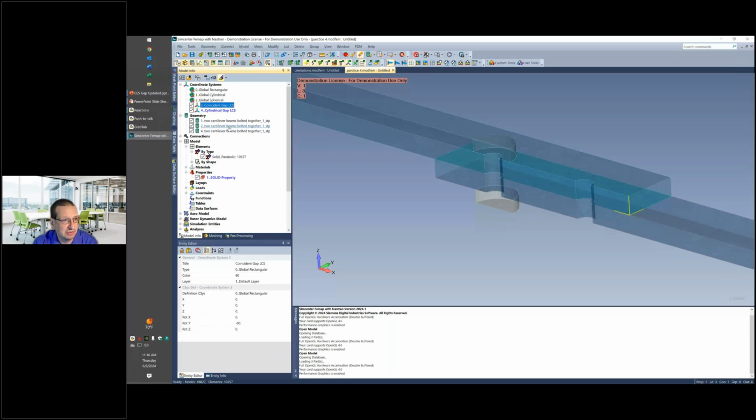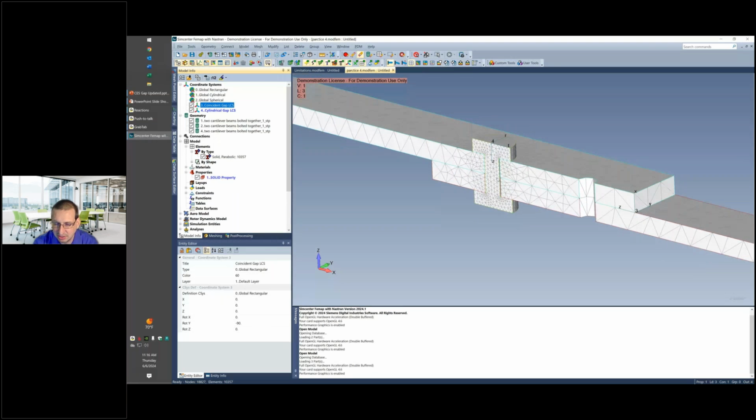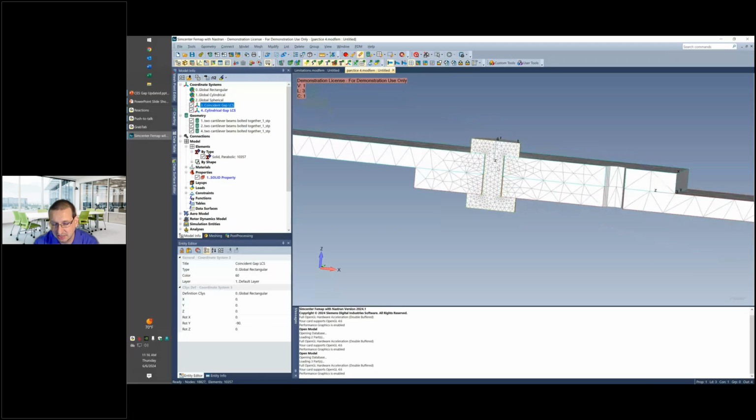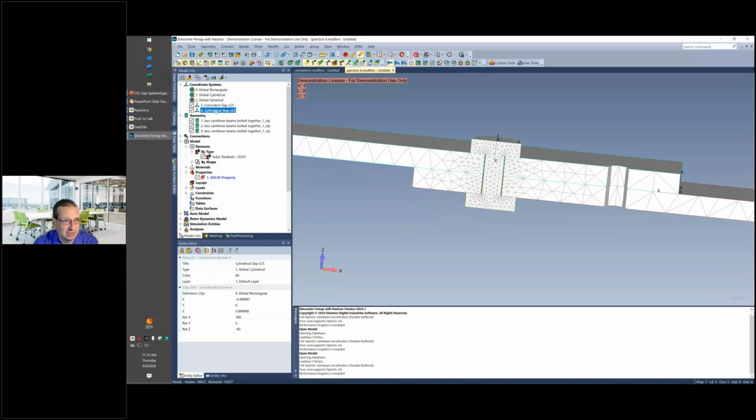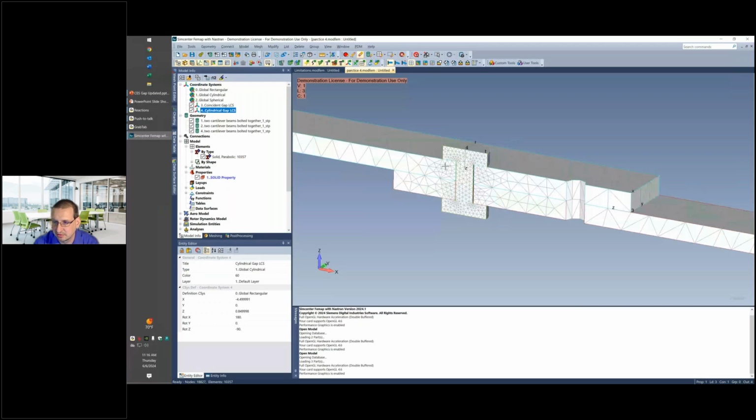And then I do have, for example, the bolted connection right here, in which I'm looking for contact between the shank and the bolt hole. We will be using gap elements with a physical gap, and I'm going to be using a cylindrical coordinate system with this one too, because it ends up being a little bit more reliable than other ways to define orientation.